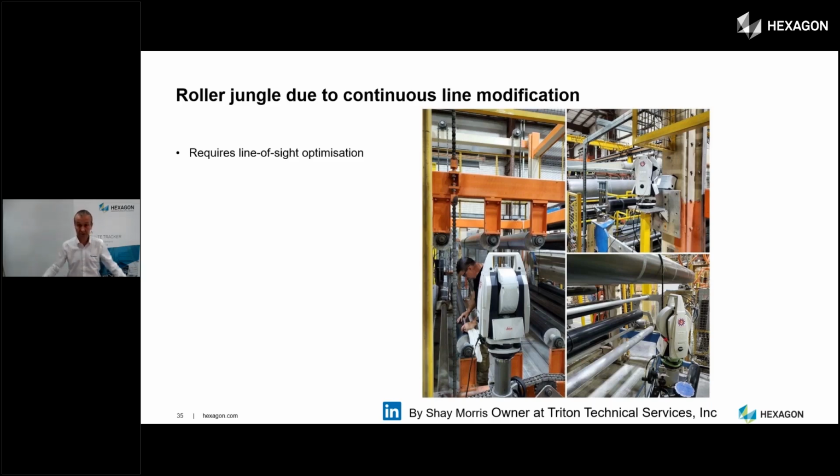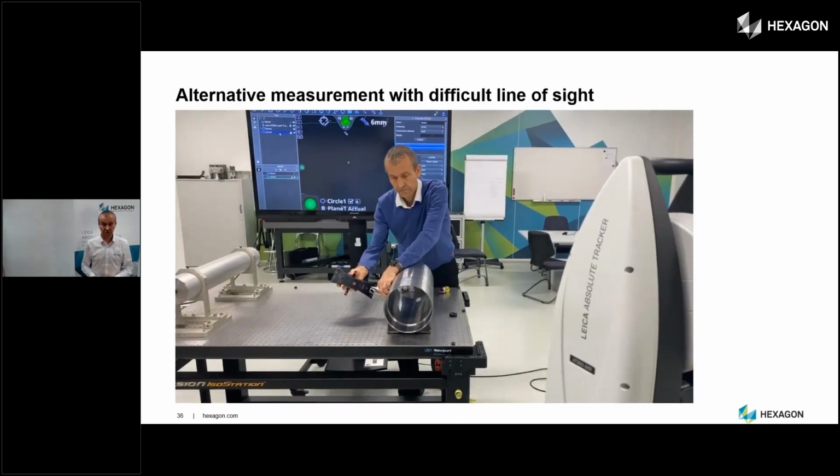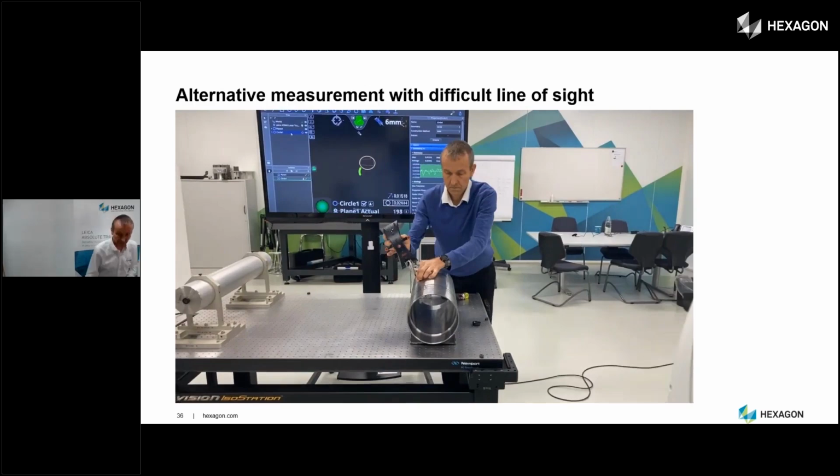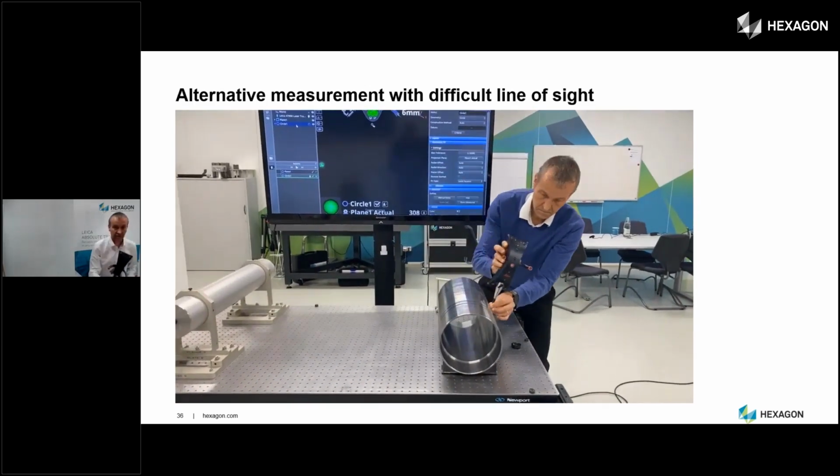And the quick process to align only 2 points, which you leave with the base plate in position for the whole alignment process, is very, very beneficial. Good. Now you are in front of the roller and you adjust, as explained before, with the roller alignment kit, or also with other, let's say, methodologies as now shown here on this video sequence. So we can also use a T-probe.